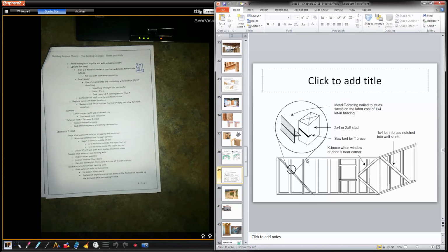So it's a kerf, and then you drop the Bailey T into that kerf and you put nails top and bottom. Okay. If there's a window in place, we have to do this on our smaller walls in the shop because we were putting styrofoam on. We had a door, so what we did is we kind of went from the same idea, from a double. So we had a king and a jack, which is solid. We went on an angle from there. So we squared up the wall, tacked it down so it was nice and square. Chalk line, cut, drop the Bailey T in, and then remove the wall from the floor. Later we'll put styrofoam onto it.